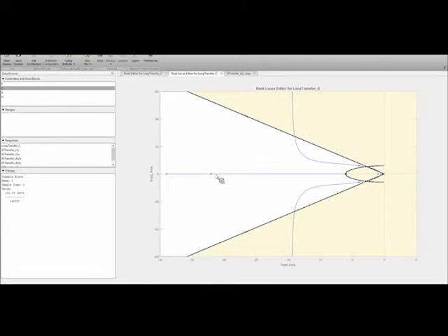Now to note, we do have a 0, and this 0, because it's an open loop 0 in the controller, is going to be a closed loop 0 as well. And we know that zeros in the left half plane are going to increase the overshoot a little bit. All right. So it's not acting perfectly like a second order underdamped system. It has extra dynamics. So this closed loop pole is probably insignificant because it's so far away, but the 0 that remains is affecting the dynamics.